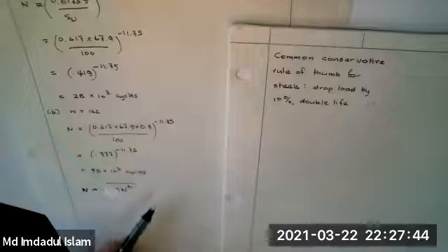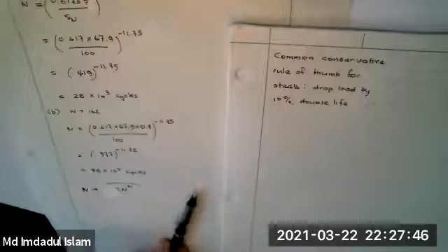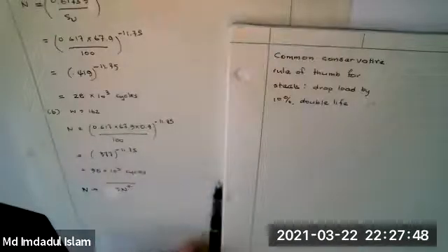Now, we'll find ways to adapt this more test to other more complicated situations, but it turns out that bending is the dominant thing that breaks things because it oscillates, whereas torque doesn't. Torque yields things more quickly than bending because it's got shear stress, but that's a yield failure. But the fatigue bending is the dominant thing.